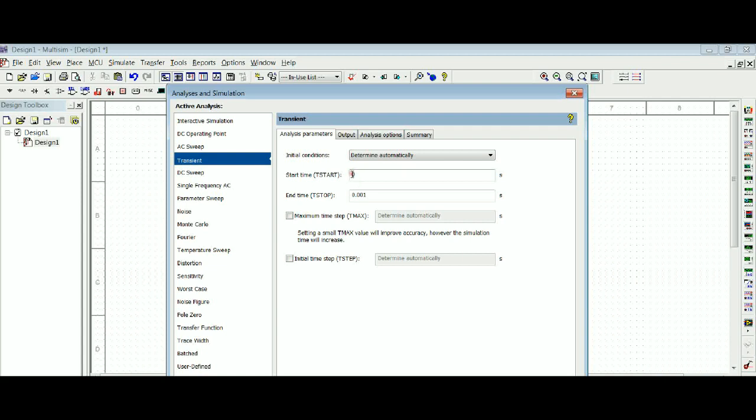what I'm going to type up here is 400, and I don't have the option of putting micro in here as a U. It won't let me do it. So I either have to add a leading 0 or enter it with E-6 to represent microseconds. Now suppose I want to look at 1.5 cycles of the signal, at 200 microseconds per cycle.